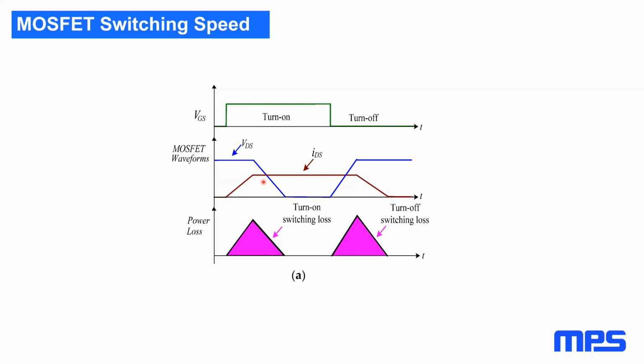How much power are you willing to dissipate in the MOSFET? And that relates back to PC board design and heat sinking and stuff like that. So generally, you want a really low RDS on so you don't burn much power. But keep in mind, a lower RDS on FET takes more to drive the gate. They have higher gate charge, higher gate capacitance. So that's a trade-off too. And I think this is a continuation of the prior question that also put in a bleeding resistor. I'm not sure exactly what that means unless it refers back to the gate discharge that we talked about before, the drain to source, gate to source resistor.